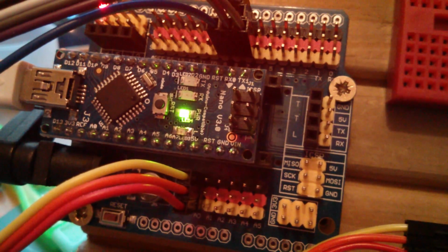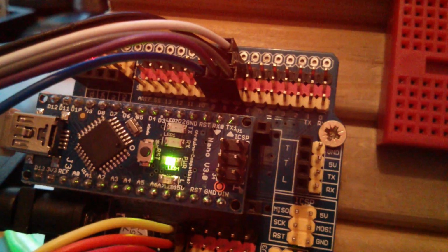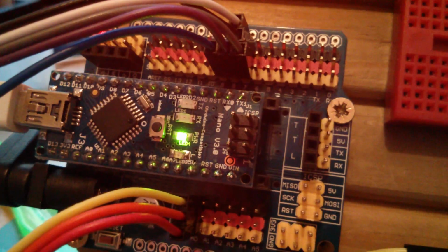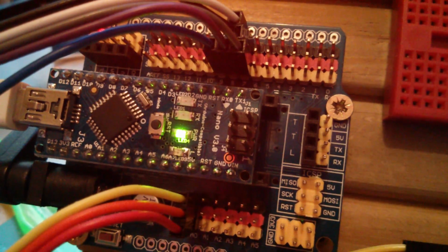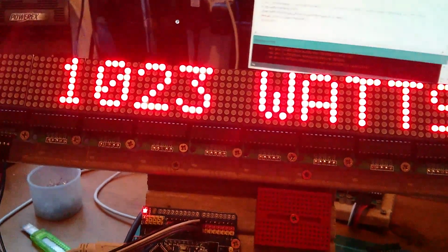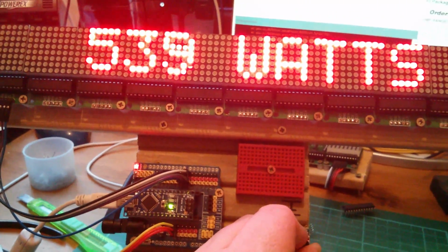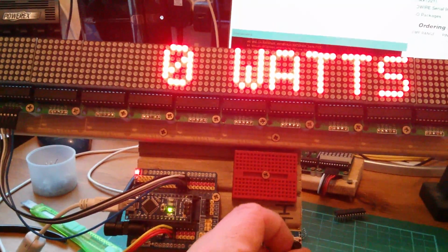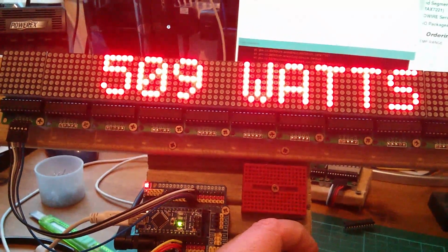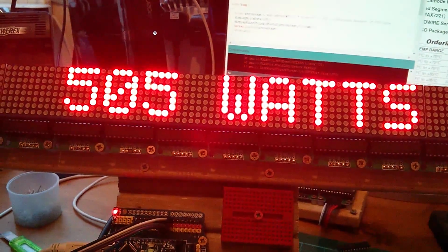So there it is, my modified board, and now the A to D inputs have the analog linear 5 volts, and the digital pins at the top have the high current switch mode power supply 5 volts, and so I'm able to draw lots of power for my display, but I'm getting the nice stable A to D measurement from 1023 all the way down to 0, and even at the midpoint of about 512 we're not getting too much noise on there.